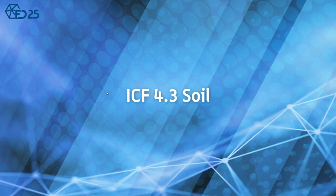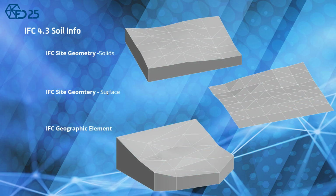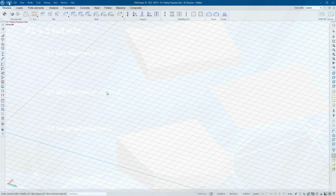Then IFC 4.3 is introduced, and the huge focus is infrastructure, and we have followed that. So we want to focus more on infra. We can now import three types of IFC infra objects. We can get volumetric site geometry out of IFC. We can also get the surface type geometry out of the IFC, and also geographic elements out of the IFC. And I can give you a few examples of how you can use it.